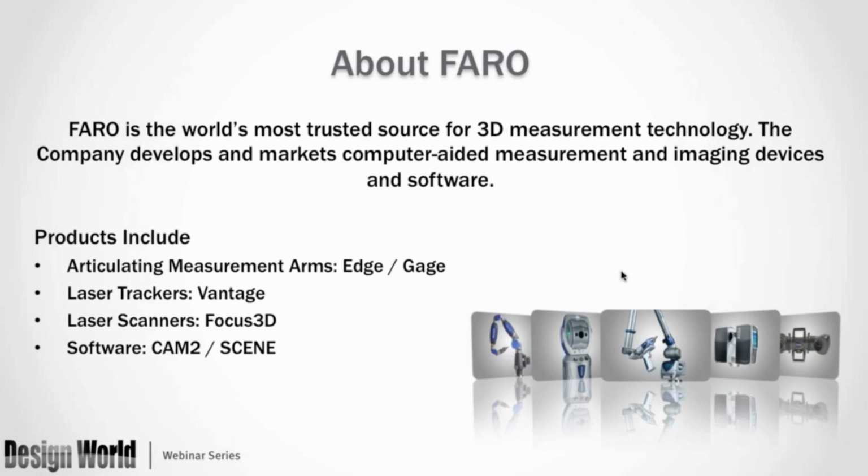The Vantage, our laser tracker, can capture high accuracy tactile data up to 262.5 feet from a single position. Also able to leapfrog, it's the ideal tool for very large-scale metrology projects. Our laser scanners, like our Focus 3D, enable large scale, and we're talking about a range of about 800 feet from a single position, with the ability to leapfrog. Mass point cloud acquisition at a rate of around 1 million points a second allows very detailed photorealistic visualizations with the ability to extract measurements from the underlying point cloud. We also have our software solutions, CAM2 and Scene. These are our own award-winning metrology software, and our large-scale point cloud capture and manipulation software.